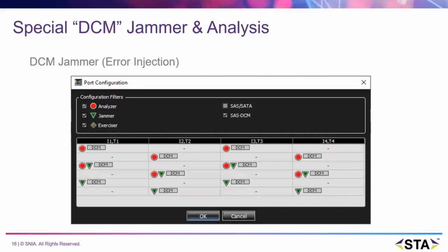DCM works by tagging each SPL packet with a channel identifier, allowing the PHY to dynamically route across multiple logical paths. This breaks the traditional one-to-one initiator-to-target model and supports cut-through routing, reducing blocking and improving overall efficiency. DCM is negotiated automatically during the link setup and is not used between initiators and targets. Instead, it enhances routing and aggregation in the SAS fabric without requiring changes to the existing SAS or SATA devices. By reducing cabling complexity and improving throughput, DCM helps extend the utility of legacy devices while eliminating fairness issues like drive starvation.